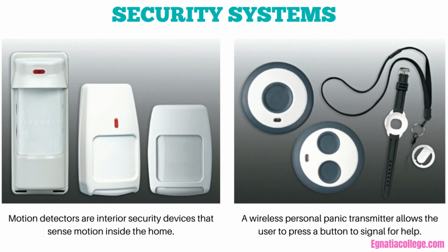When such detectors as door entry, glass break, floor mat, and window foil are used, circuits are electrically connected in series so that if any part of the circuit is opened, the security system will detect the open circuit. These circuits are generally referred to as closed or closed loop. Alarms, horns, and other signaling devices are connected in parallel, since they will all signal at the same time when the security system is set off.